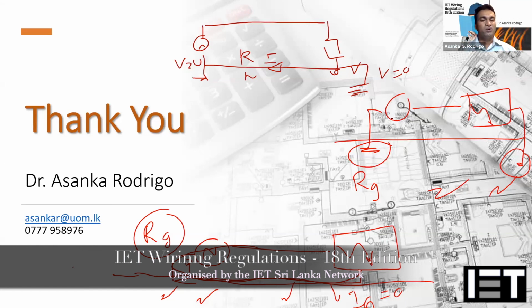Yes, we can go, because that is the best option. Normally, if we can protect all the circuits with the RCBO, then that will give the earth fault protection as well as the overcurrent protection. But the main reason is the cost, because there is a cost difference. But if the client is willing to afford it, then the best thing is, if we can convince them, we can go with the RCBO.